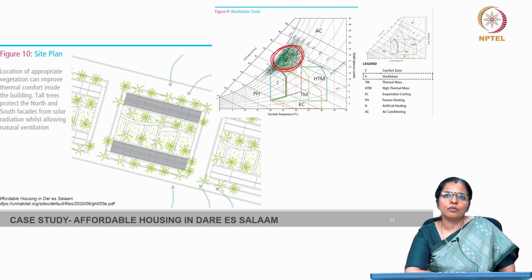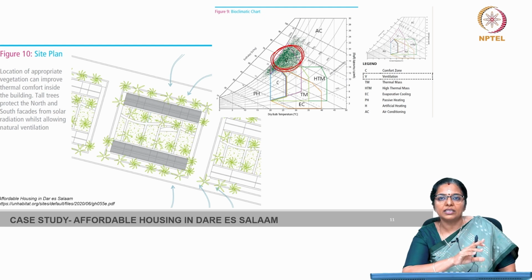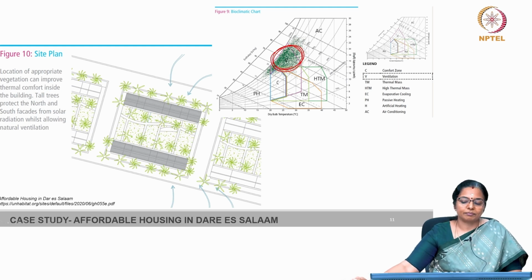The interpretation of this design approach indicates that during the period from January to March, maximum temperatures surpass the range suitable for natural ventilation. Because bringing in natural ventilation during a very hot period is like bringing hot air inside. Furthermore, the preference for open and non-compact building structure is highlighted as a strategy to amplify ventilation and contribute to overall thermal comfort in this climate zone.